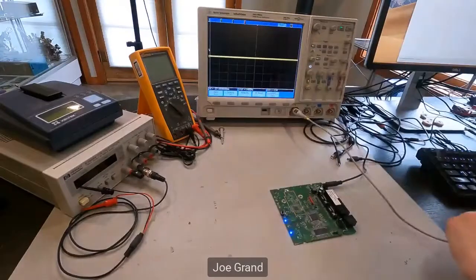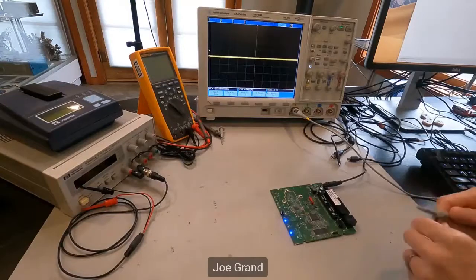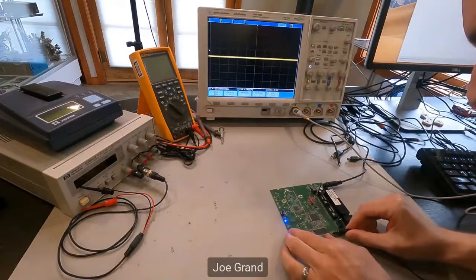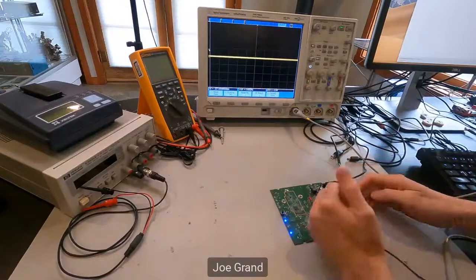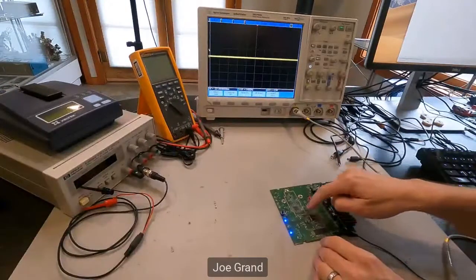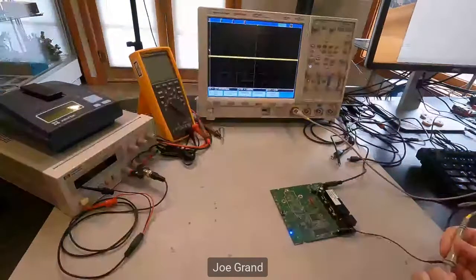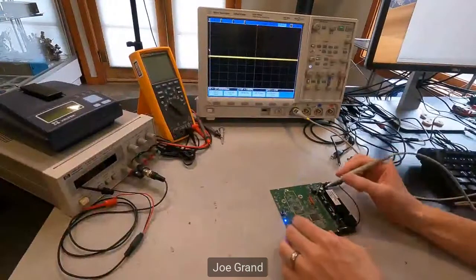Like with every tool when you're dealing with electronics, you have to identify a ground connection. Ground is really the 0-volt reference, this kind of shared reference. I've already done that, and I've marked it on this board. Generally, if you don't know what it is, you can look at the power supply section, look for the negative side of a capacitor, or look at the data sheet for some of the components, because it will tell you. We need that so when we're monitoring or injecting signals, we're all at the same common reference.